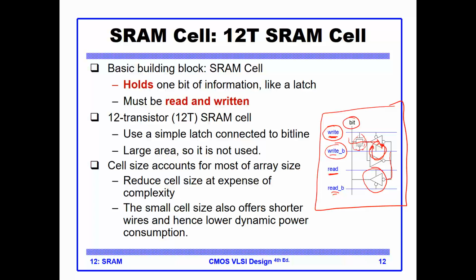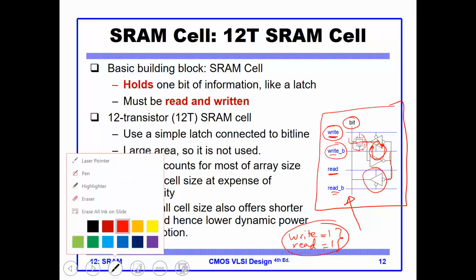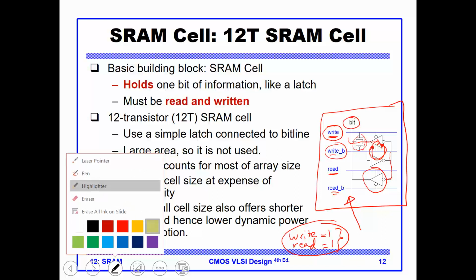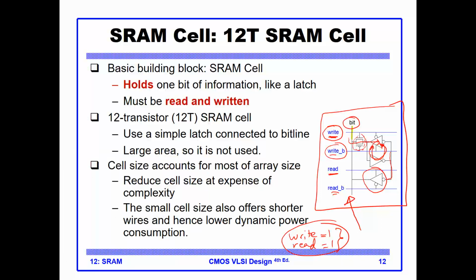It is important that this condition, write and read signal are not one at the same time, because if they are one at the same time, you will have a collision on this shared bit. This is a shared resource, which is the bit line.